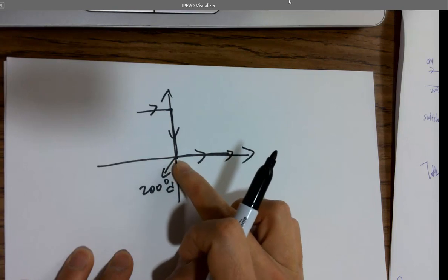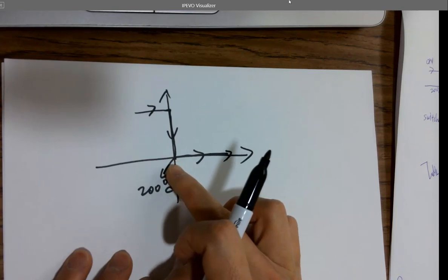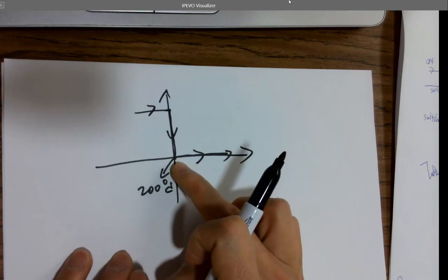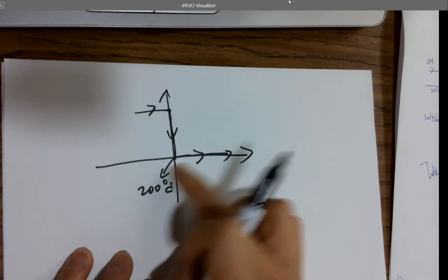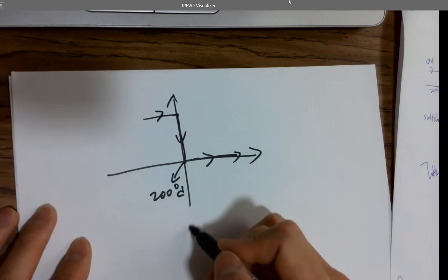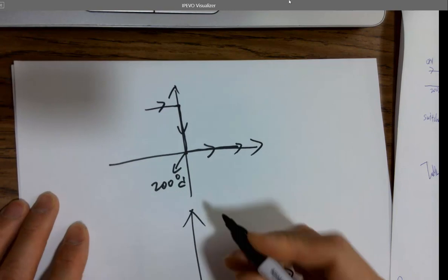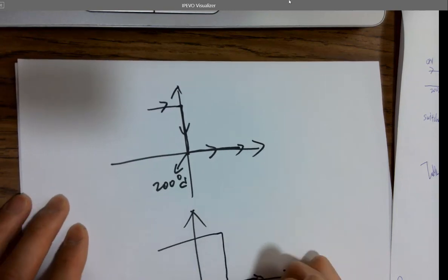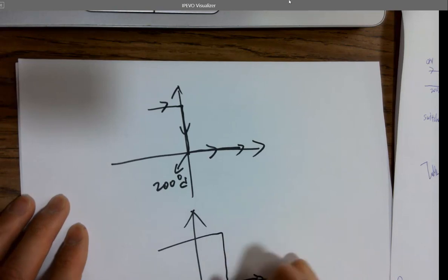It's similar to the HVAC in the house, right? The thermostat. You don't want it just at one point at the threshold temperature, because it's always switching on and off. It's really annoying. So really, a desirable design is that you have a hysteresis. For example, the set point is still 200 Celsius for the oven.